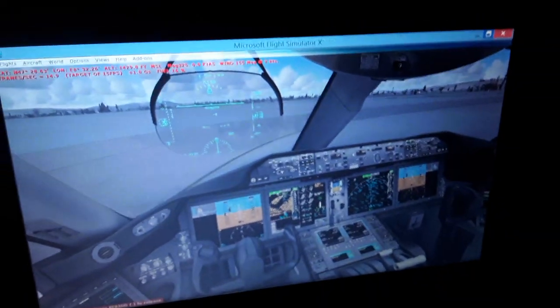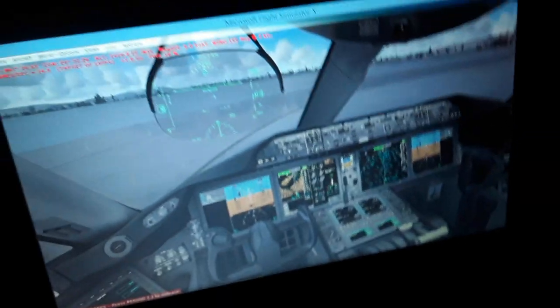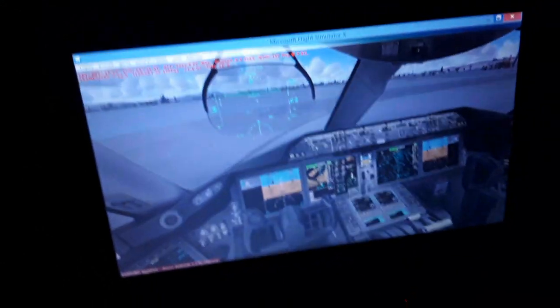I'm going to start with the primary flight display. The displays are the airspeed indicated, the airspeed selected from the autopilot and flight director system panel, the ground speed, the radio altitude above the ground level, the barometric altitude above the sea level, the vertical rate of climb and descent of the aircraft in tens, hundreds, and thousands of feet per minute, and the steepness of the trigonometric angles in degrees you can climb and descend.